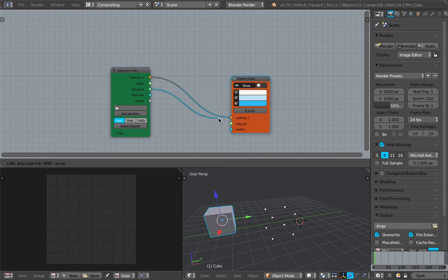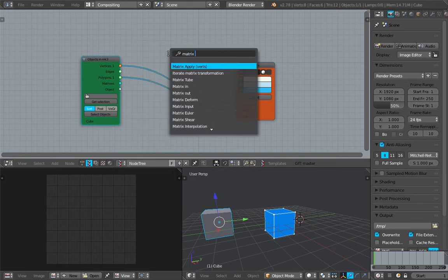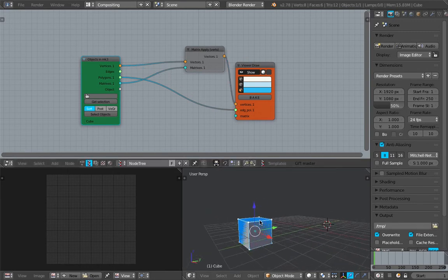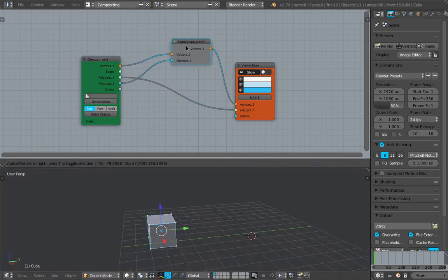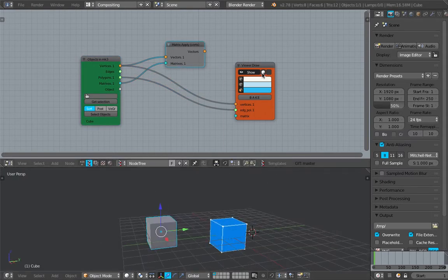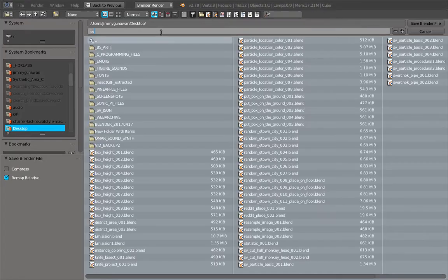It's gonna still be at 0, 0, 0 unless we use the matrix apply here. If we apply the transformation of the object, of course the result in Sverchok will follow that particular 3D object. If we don't use the matrix apply, it's gonna still be at the 0, 0 position. So that's taken care of. I'll save real quick. This is Bisect visualize.